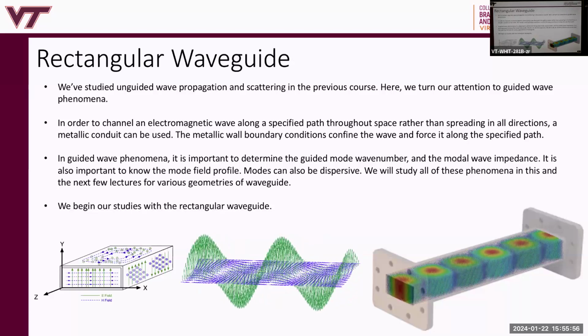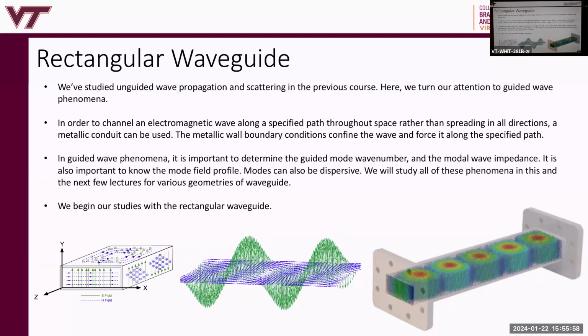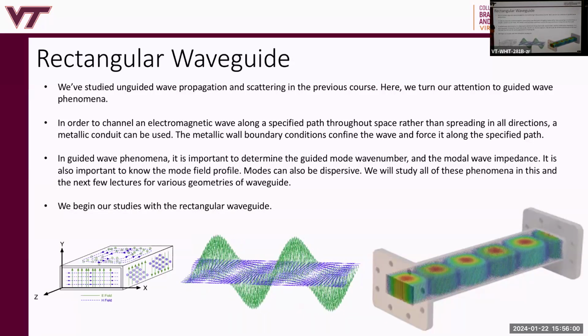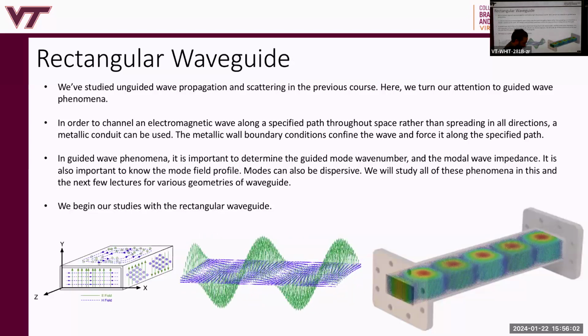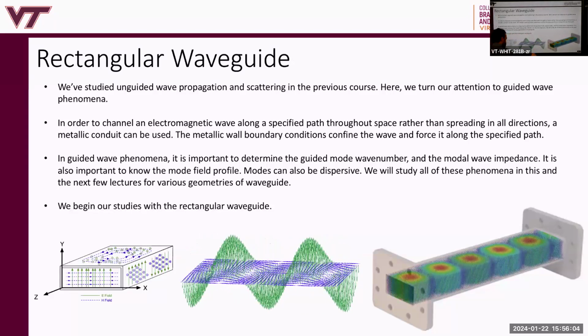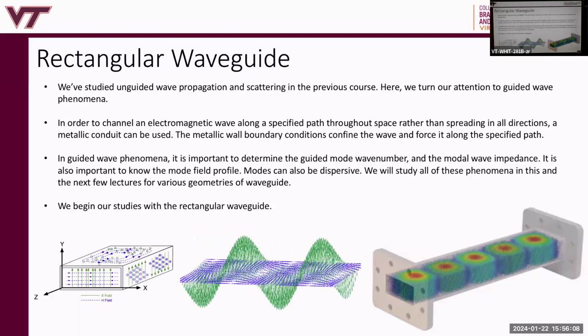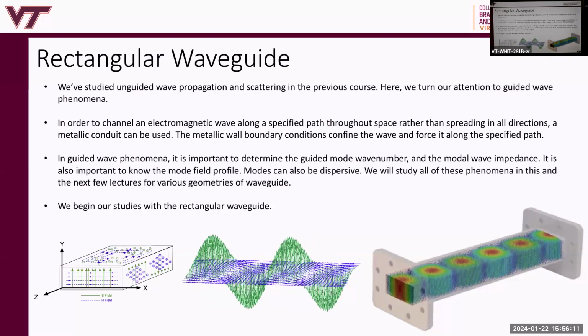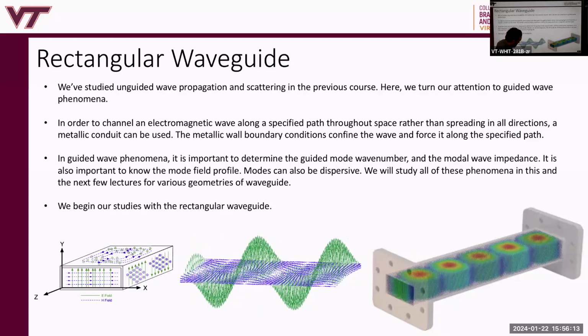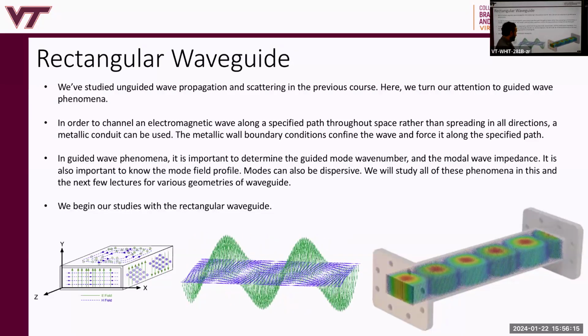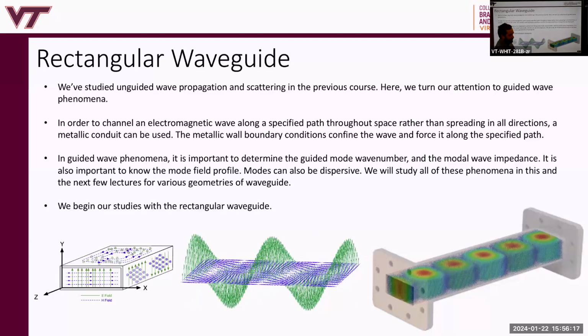Because I've read it. So perturbation can mean a lot of things, right? Yeah, that term is used for a lot of different concepts, but the one that we're going to study in this chapter refers to keeping the original modes that we derived from lossless walls, for the lossless waveguide, when we analyze the loss of it.